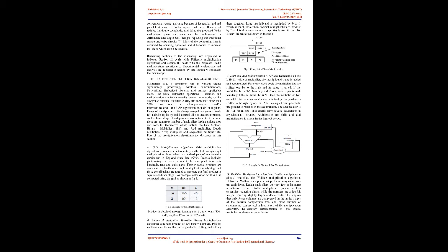H. Goyal et al. 3 implemented a fast multiplier based on Vedic mathematics using a modified square root carry select adder. This method reduces the carry propagation delay. Since adders are main components used in multipliers, using fast adders definitely enhances the overall performance of Vedic multipliers. Various adder topologies like ripple carry adder, RCA, carry select adder, CSA, square root carry select adder, SQRT CSA, etc., are used to compare area, delay, and power.